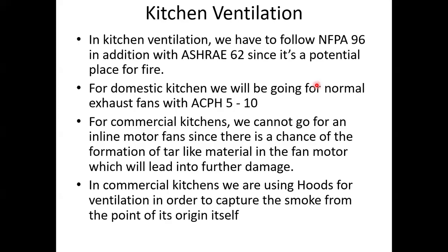But especially for commercial kitchens, the normal exhaust fans won't be enough for those assemblies. Why? Because the difference between commercial kitchens and domestic kitchens is the usage of the area. Commercial kitchens will be frequently used, so there is a chance of formation of tar-like material.